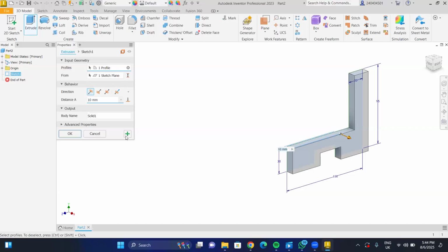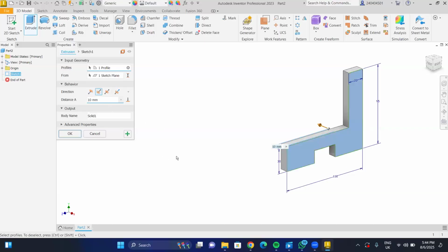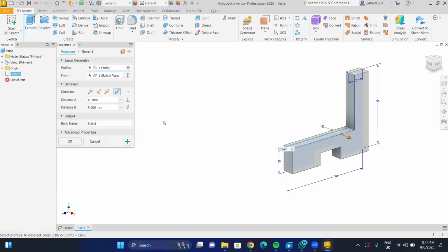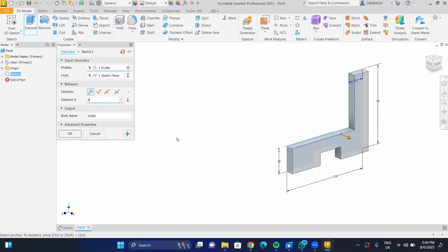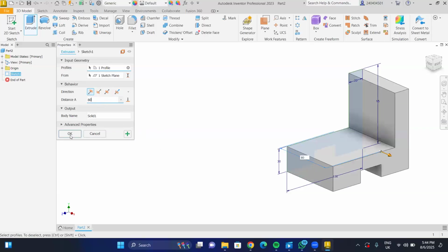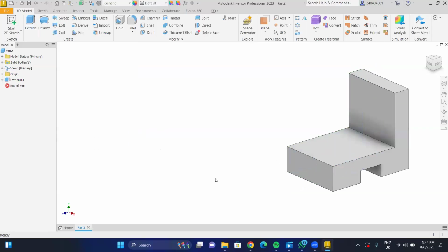Now the extrusion has different options. You can either use this or change direction, or use the one that will separate into two equal halves, or the one that will give you an eccentric offset. So you can just choose any one. Okay, let me choose this one. We said that width is 80, so I'm going to just click on 80, and that gives us the entire block. So we have this.